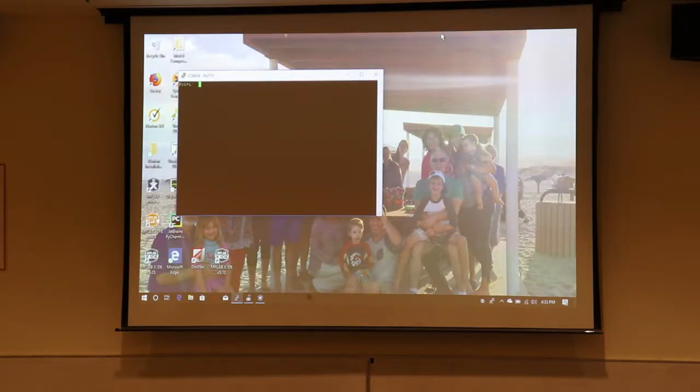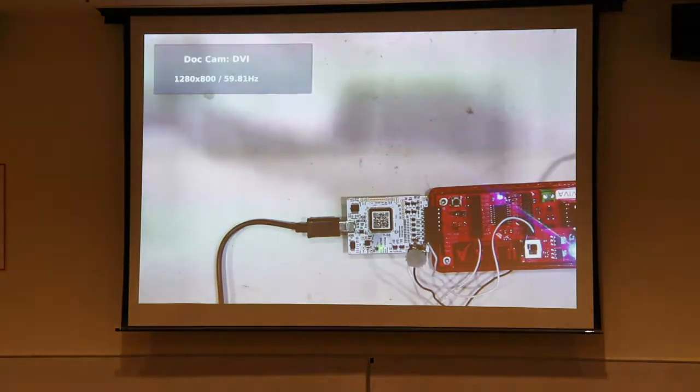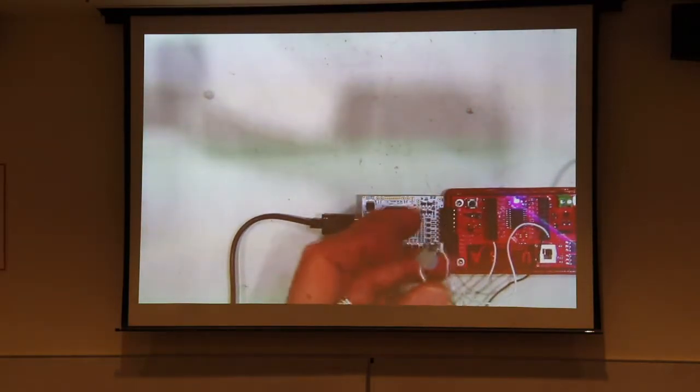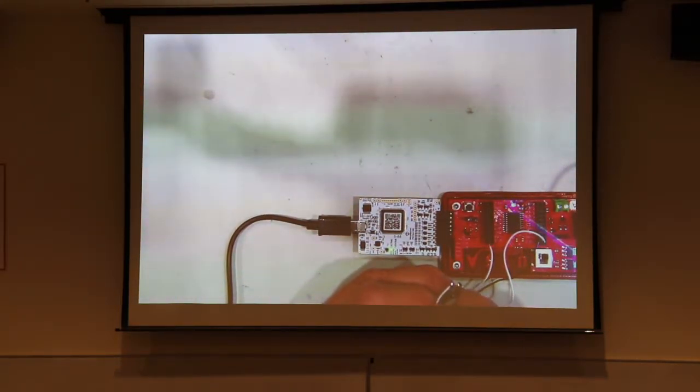All I do is write the duty cycle value in the register. So I can change this. If I put it, say, at 512 or something like that, it should be at about half brightness. And you can kind of see, that's kind of what it is. It's about half bright, and then as I go down. But the nice thing is I have pretty good control over it to make it go pretty much the full range of values here.